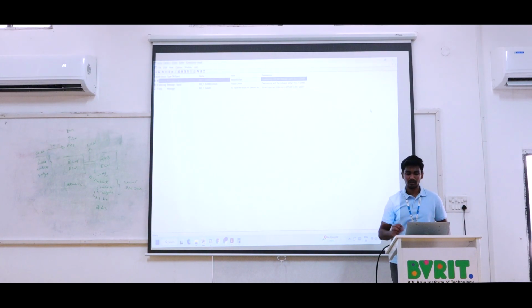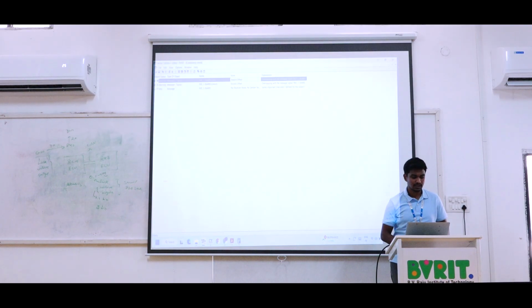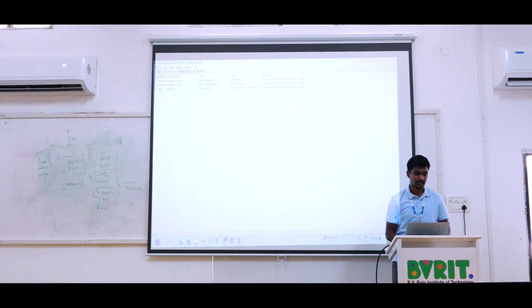In our editing, if something is overlapped, we can check it in the consistency check and clear it. You get this information by going to the File menu at the top left, where we have the Consistency Check option. Once you open the consistency check, we will see the errors we made during the creation of the database.